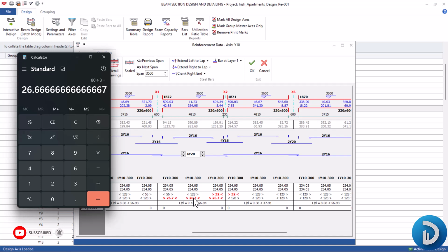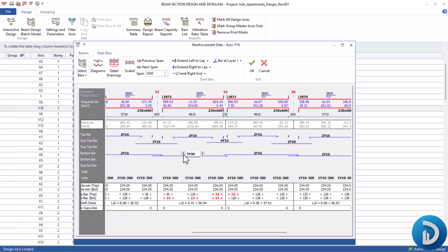Okay, then the question is, what happens when we can no longer ignore this error? Let's say we are having five numbers of Y25, and the spaces between those reinforcement has turned to 8.8 millimeter, which is way below our aggregate size.